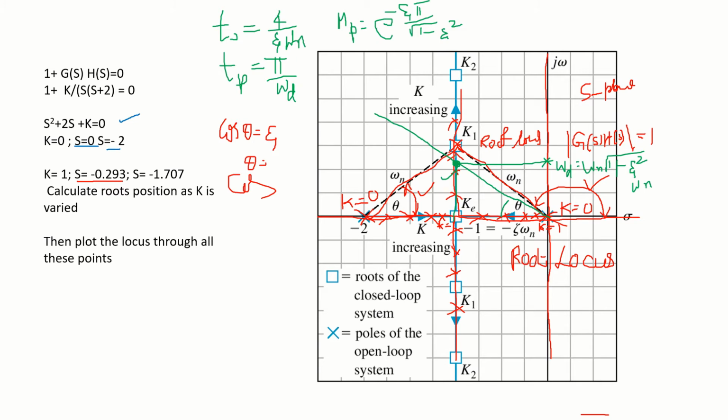So for that, what is the corresponding value of the parameter? Now, once we know that these closed loop poles are there, then you can bring them back and you can get the characteristic equation. Probably now we can work backwards, right? We know the system parameters. It becomes easy for us to design the system to meet the required specification. So once we have the root locus, we can find the K value, then we can find the closed loop pole configuration which meets our transient response specifications.